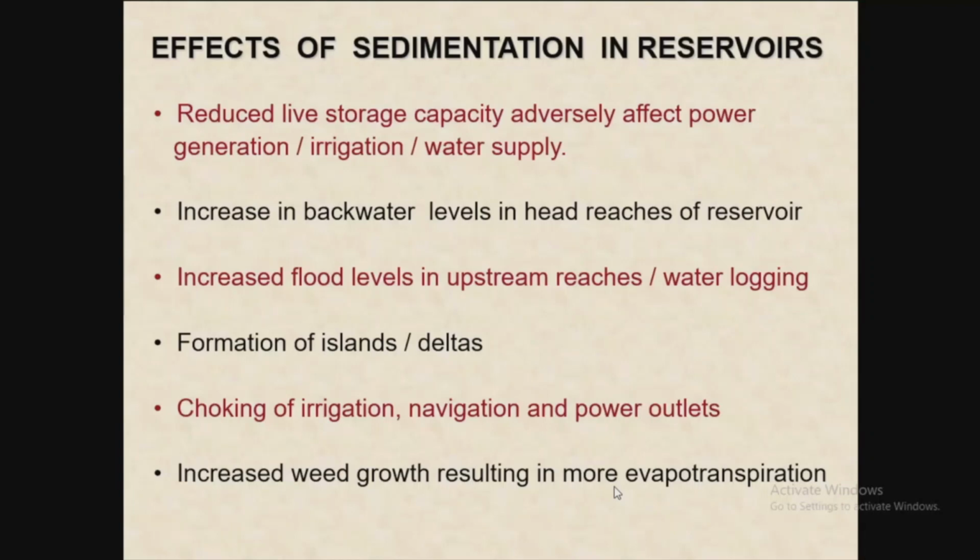Now, what is the effect of sedimentation on the reservoir? Why are we bothering ourselves to calculate the reduced capacity of the reservoir? The reduced live storage capacity adversely affects power generation, irrigation, and water supply. I told you previously also, because 20% is reduced, we cannot use that capacity. And increased backwater levels in the head reaches of the reservoir create the problem of flooding in the back reaches, because that level we have not calculated because of slopes.